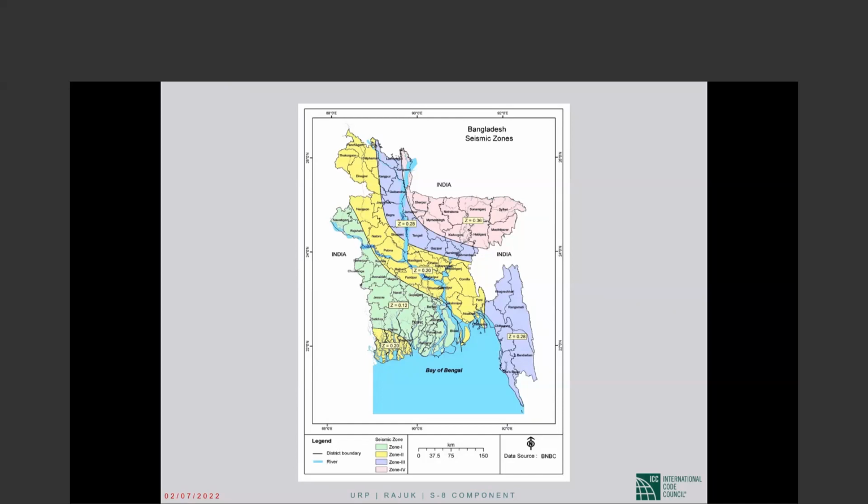That is a huge problem. This is the problem with infill masonry, as we call it. Not only in Bangladesh, pretty much everywhere that brick infill is used, the infill is not reinforced. So initially, the infill contributes to stiffness, and the building has very high stiffness because of the infill. But then in an earthquake, the infill is among the first to fail. It cracks diagonally, and then it can just fly, even killing people.